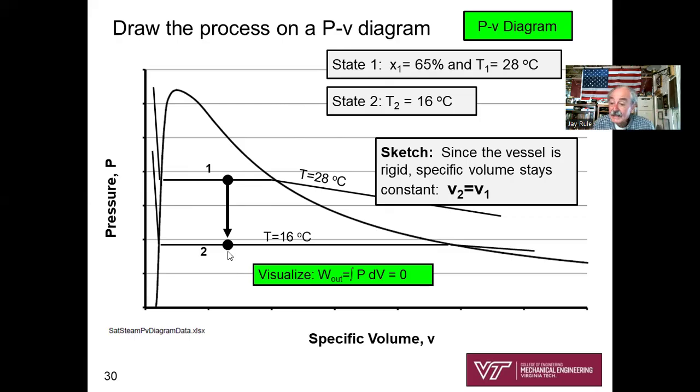Can you visualize the work out from this PV diagram? What's the integral of PdV? 0. There's no change in volume. dV is 0. So mathematically, the integral is 0. So we're halfway there already. Work out 0.